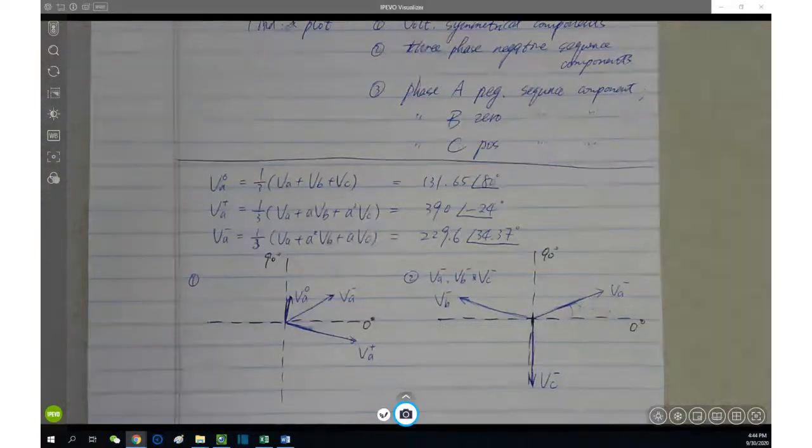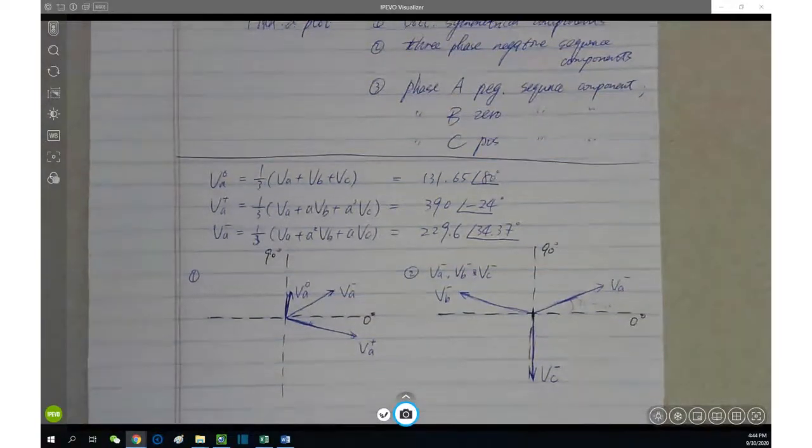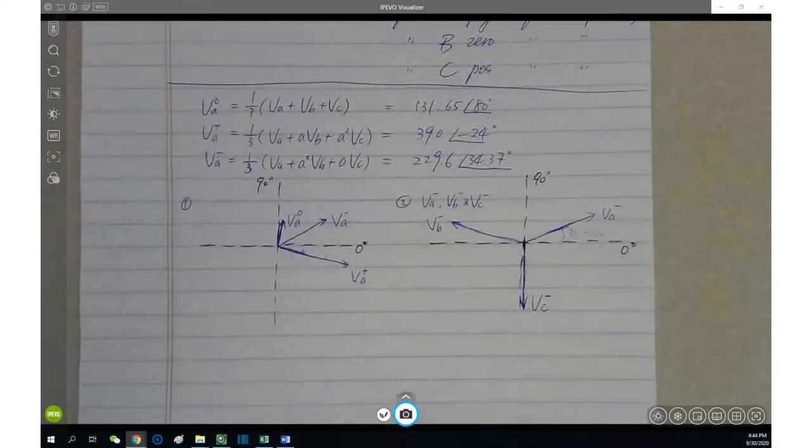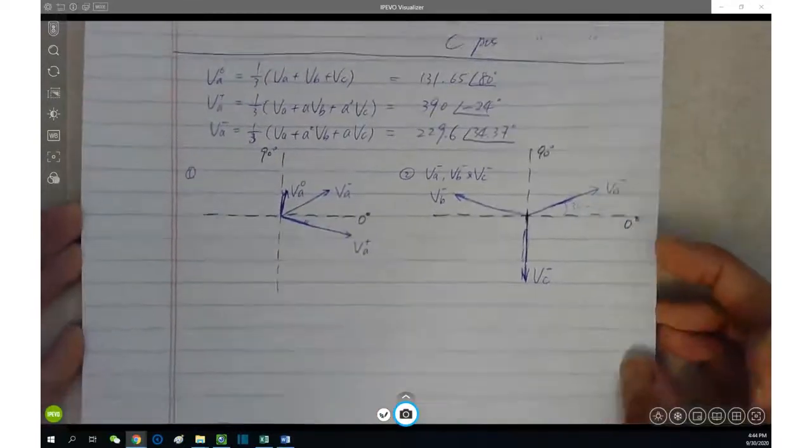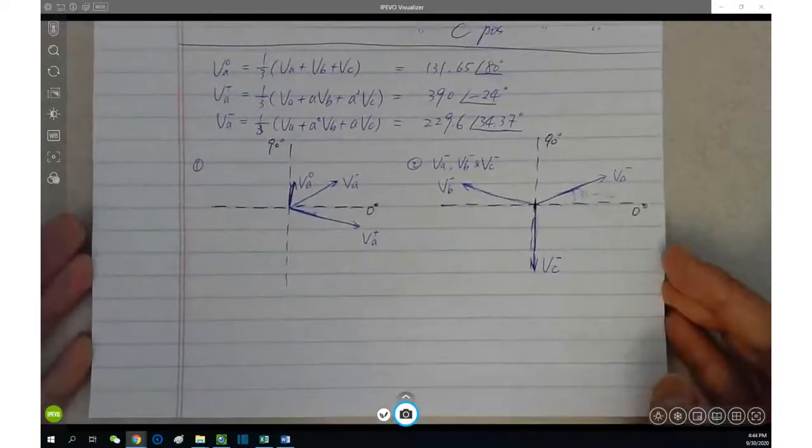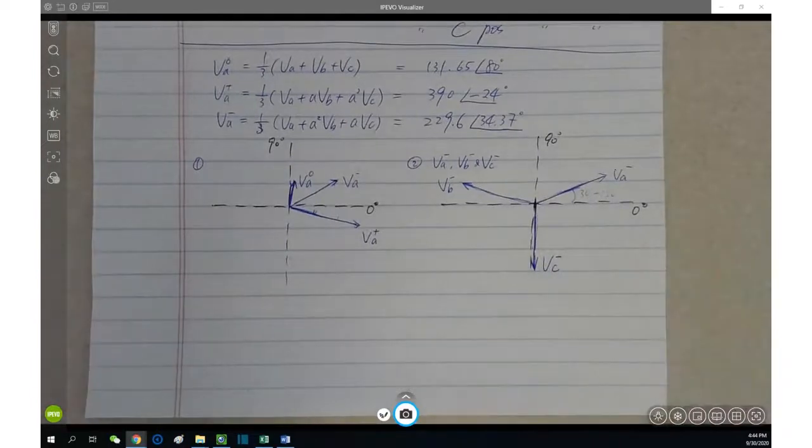So just to make sure, with this negative sequence, if they have a 120 degrees difference between each individual one, and the same magnitude, that would be considered a balanced load, right? Yes, yes. So basically, no, I'm not talking about balanced load. I'm only talking about the sequence. This particular sequence they're balanced.